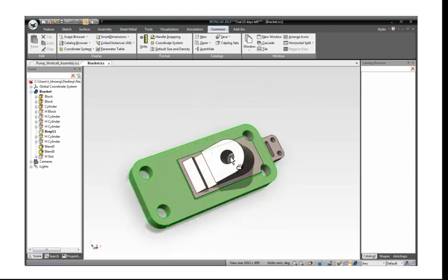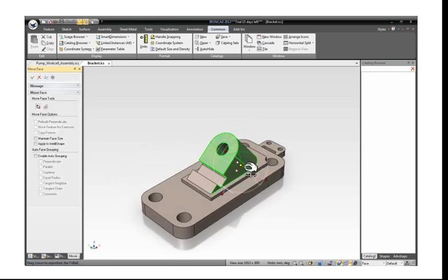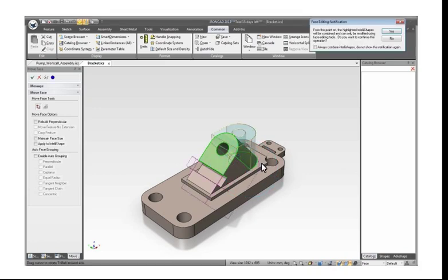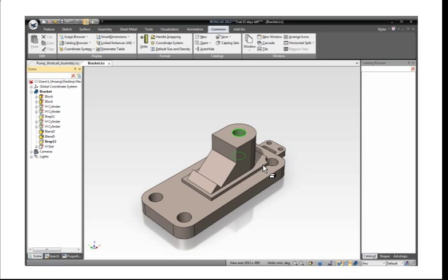We continue the modification by making edits to the part for the bracket so it can support the vertical object. Again, we use the triball to position the faces of these features. As you can see, the system shows you a preview of the direct editing results and highlights the features that will be affected by the direct modification with a magenta highlight. Also, the system asks the user to confirm if this is really what they want to do. If the user confirms this modification, then the system will take care of all the changes. In this process, the designer only needs to focus on doing the modification they want to achieve the desired task.